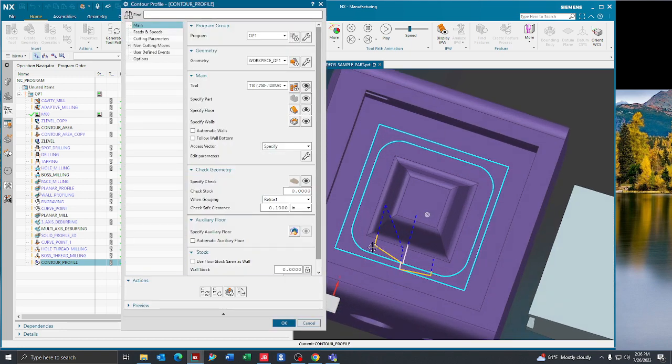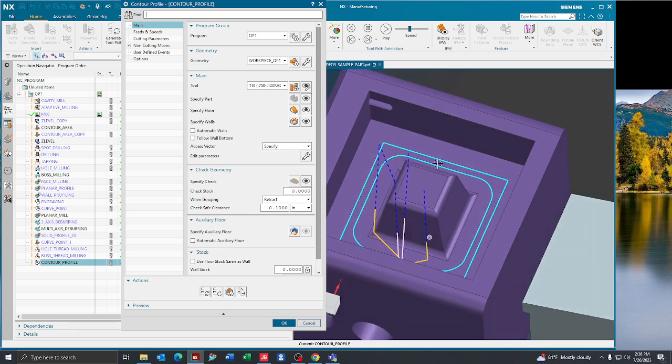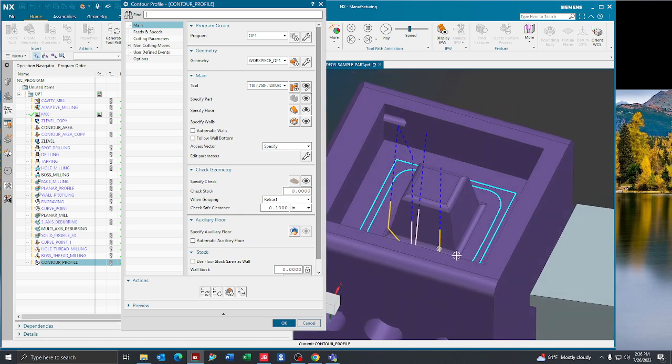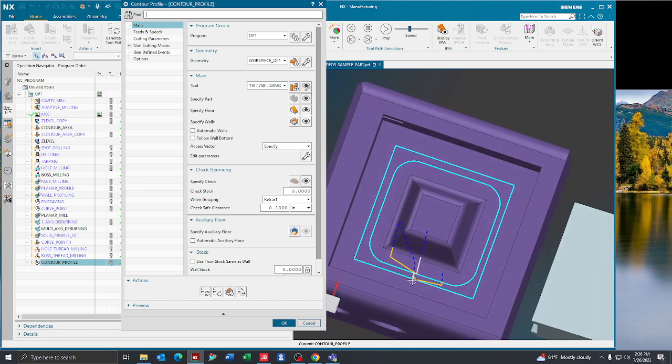Here you can see that it has the same internal toolpath going around our tapered feature, but since it pre-selected the outer walls of the pocket as well, since they contact that floor, it did 2 passes, one around this tapered square and then one on the inside walls.